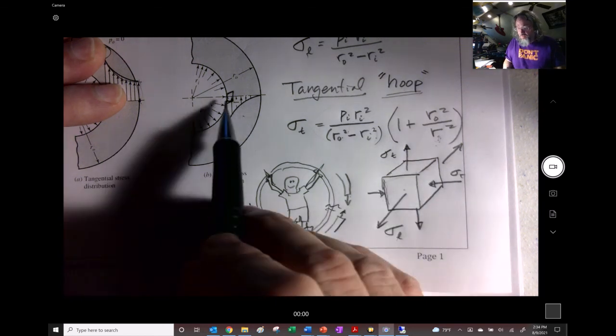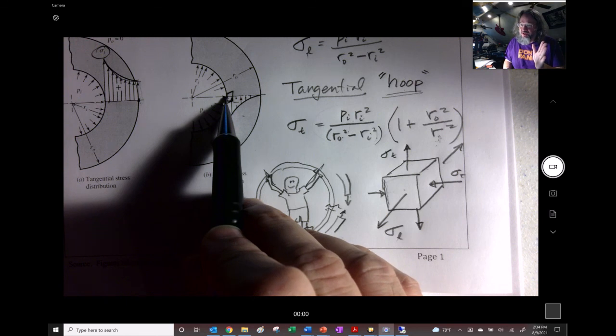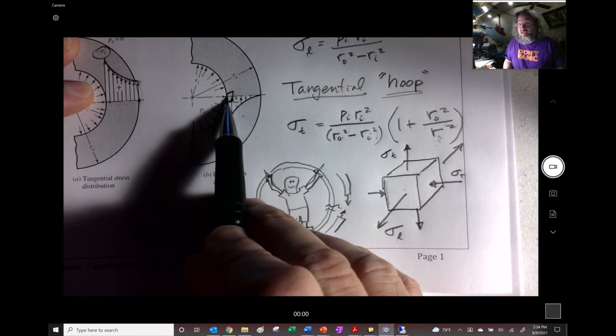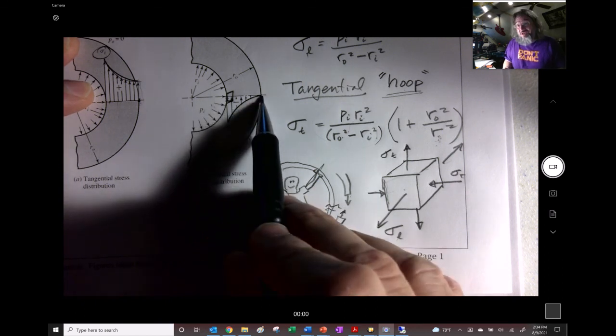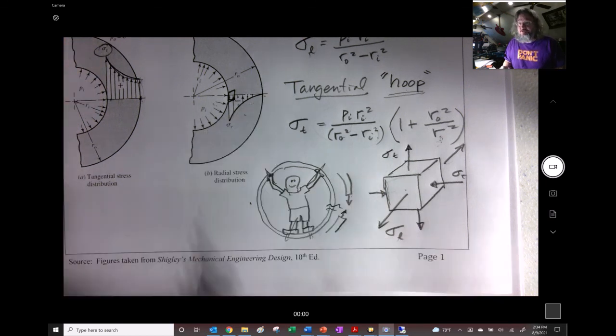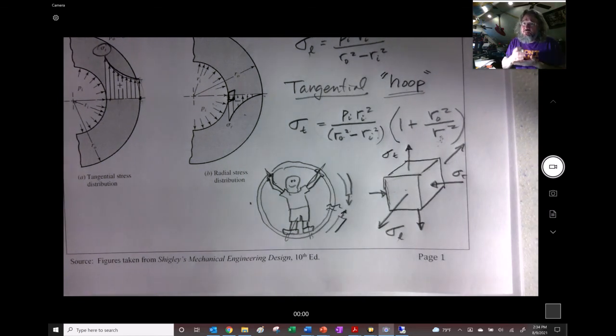Notably, the radial only really matters, and most of the time we're always looking at surfaces of things, so it's only on the inside surface of the pressure vessel where the radial actually matters and will be anything. Most of the time, a lot of times, we'll be looking on the outside surface. Unless told otherwise, we're probably looking on the outside surface, and radial is 0. I find that students get obsessed with the radial only in special circumstances when we're on the inside surface of a pressure vessel. Are we ever going to consider the radial stress?